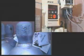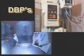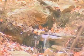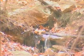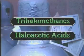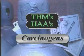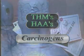Another benefit is the diminished threat of disinfection byproducts. Disinfection byproducts, also known as DBPs, are a result of natural organic matter found in the water combining with chlorine to form trihalomethanes, THMs, and/or haloacetic acids, HAAs. They are both considered carcinogenic substances, and water systems are required to meet maximum contaminant levels on each.